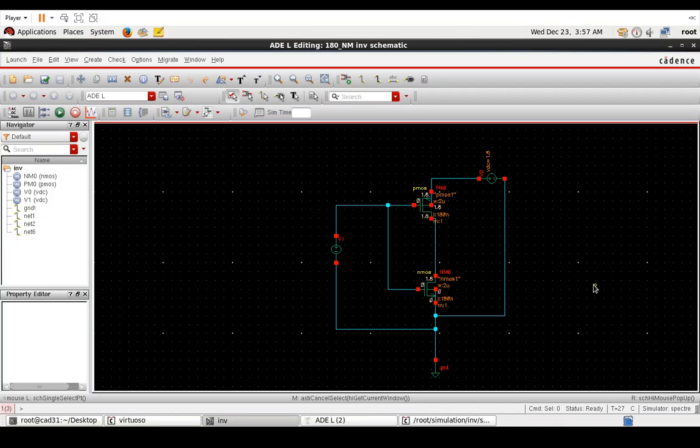Okay, so if I want to change this, the question might ask, make the inverter threshold 0.9 volts, which is VDD by 2. Okay, now it was 0.75 volts. If you want to increase the inverter threshold, you have to increase the PMOS transistor.